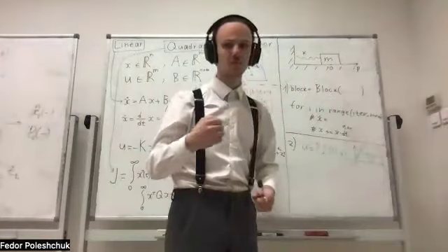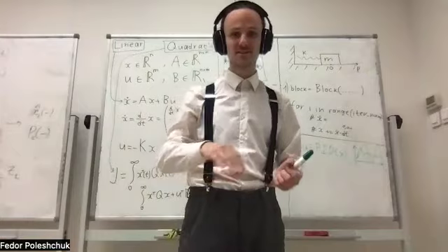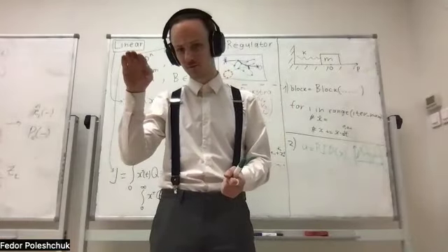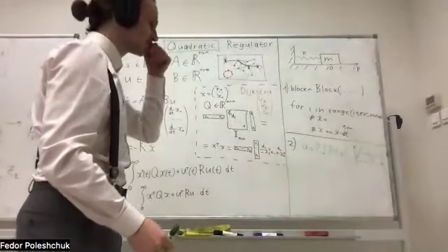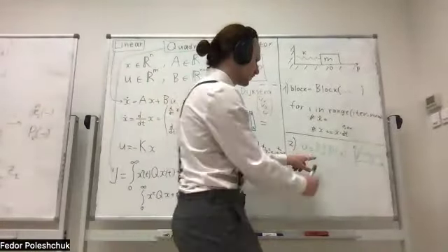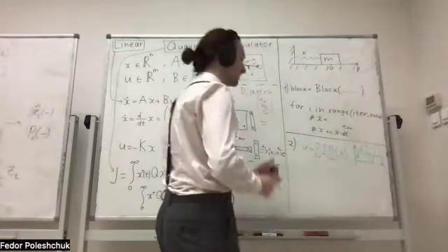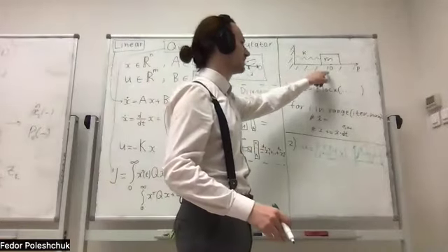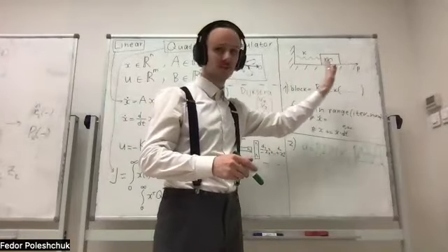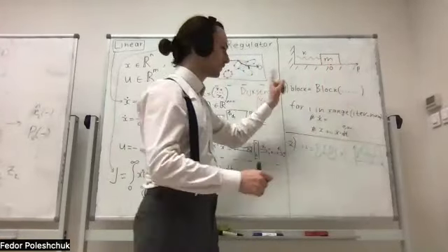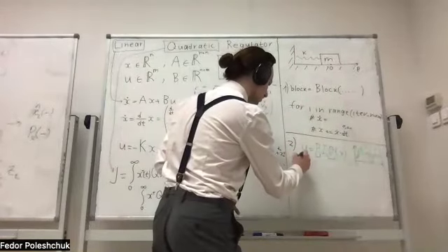If you set a proportional coefficient to 0.01, the system will slowly converge, but it will take a very long time. That's not cool. So try to experiment mostly with these two coefficients. The integral coefficient could be set to 0 because, in this exact case, there is no static friction, no constant offset, but you can try out its problem, say 2 star.